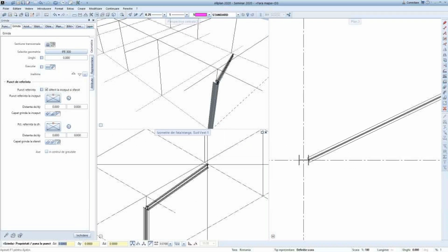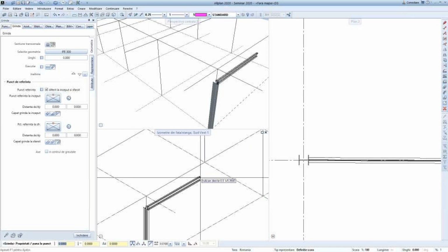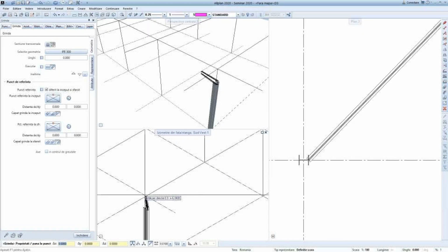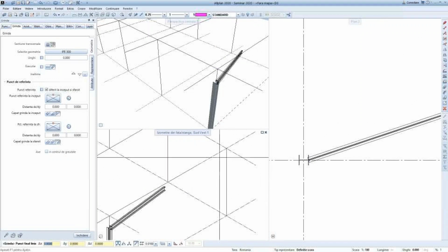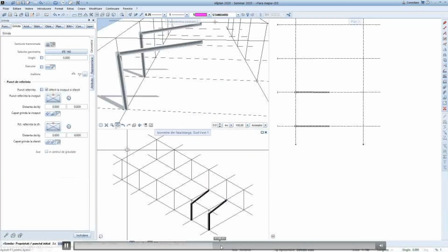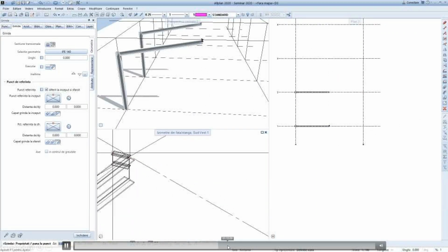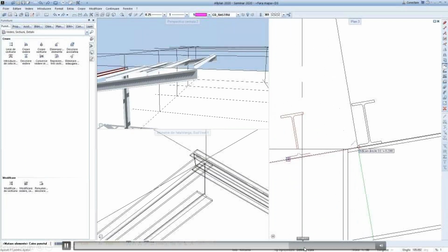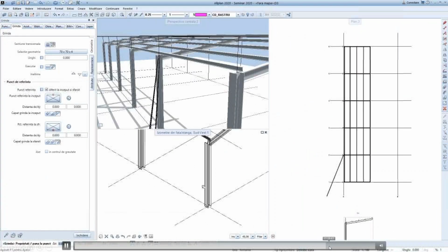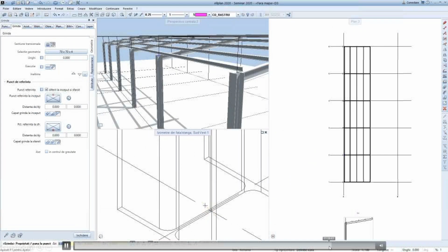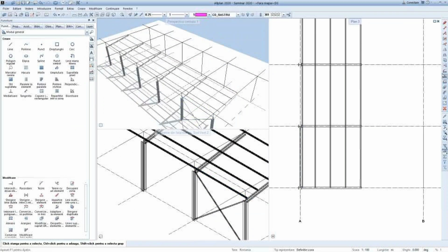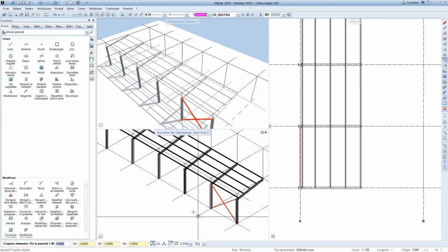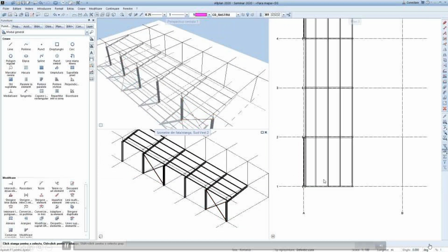So you see it can be cut vertically at the face, and then it's easy to connect to a slope. Okay, and I'll just go through it. You make it inclined, but everything stays as a database. So you see you can change the geometry later, and everything is related to a grid and can have eccentricity. So now it's easier, at least for purlins within the structure, and for bracing as well. Making bracing was a nightmare with previous versions. Now with skeleton modeling, it's even easier.